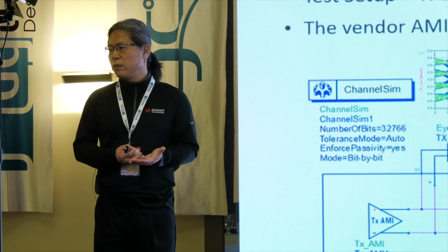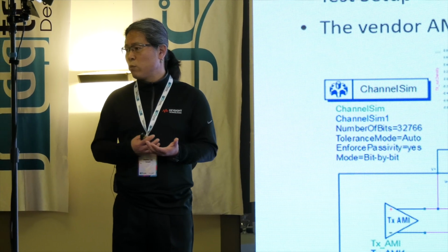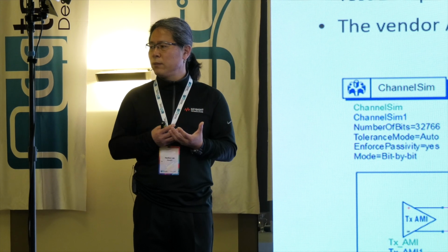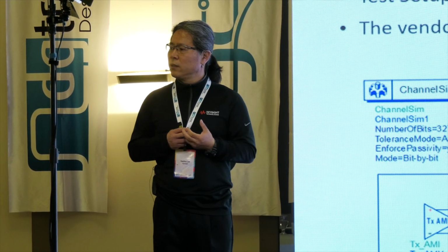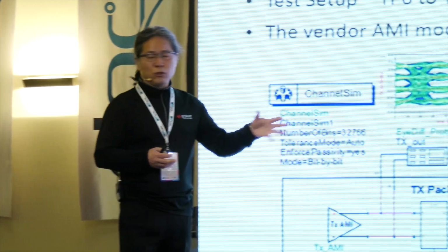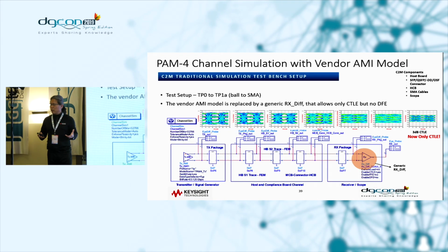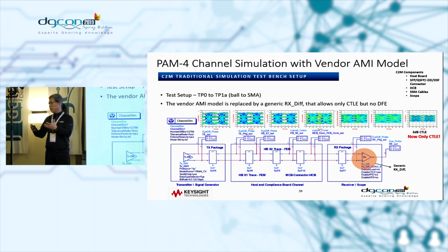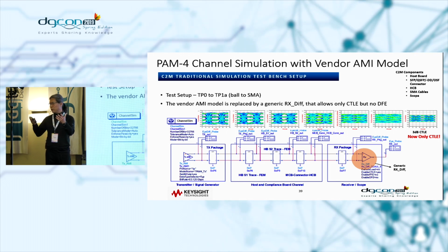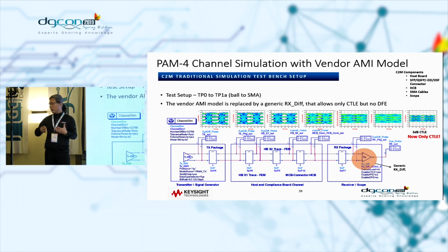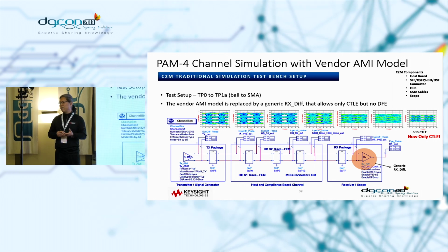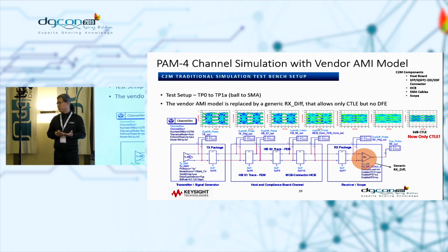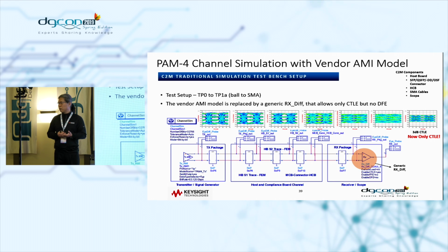That's another great question, where I always feel there is a little bit of uncertainty. For example, when you put in the generic model, how do I represent the chip's package information properly? And when I use the IBIS AMI, which comes with its own package models and so on, I cannot really get rid of the DFE. How can I do that? This is where engineering judgment needs to be made properly.